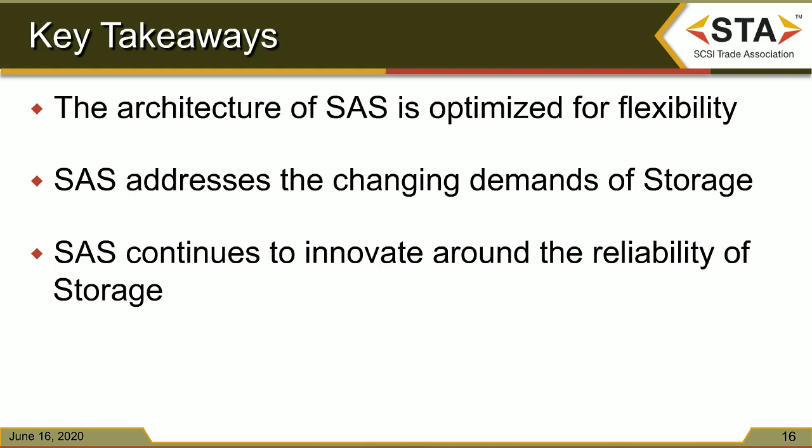And then finally, like just what Tim was discussing, that T10 has been focusing on very specific innovations and features like forward error correction, like continuous adaptation, or the real name, active PHY transmitter adjustment, in order to maintain the robustness and reliability of SAS moving into 24 gig. And with that, let's look at some of the questions.